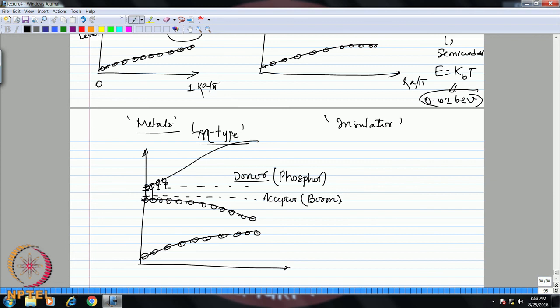What happens is, from the semiconductor material these electrons can jump to the acceptor energy levels. They cannot jump to their own conduction band, and therefore excess empty spaces or holes are created. So, in the base material you have holes, and therefore this becomes a p type semiconductor.